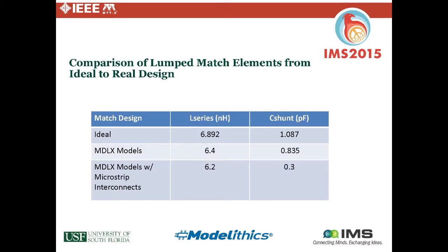If we're solving on a Smith chart, we're going to normalize that and plot it. Then we rotate through a transmission line of characteristic impedance Z0D, and we arrive at this impedance. This is the input impedance, and we can calculate that analytically, or we can determine it from the Smith chart.